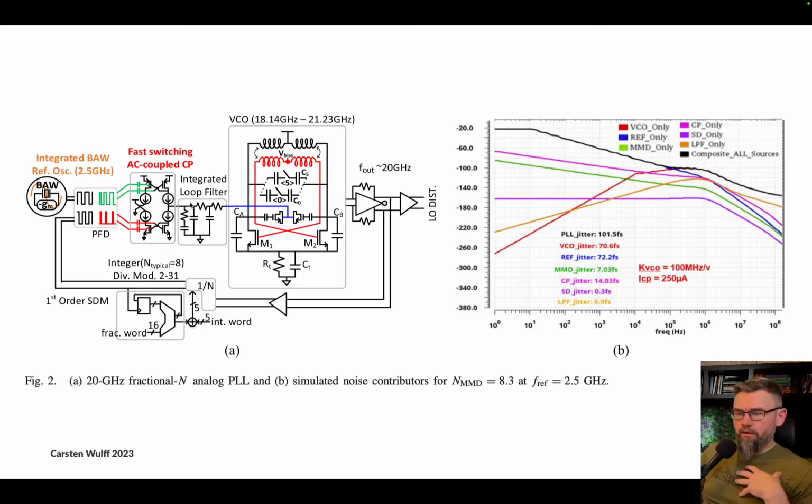Okay, then we have a loop filter, similar to what I showed you, but there is a second filter here, a voltage filter. So the first part is more current, generates a voltage, and then we have a low pass filter. And that feeds into an oscillator where we control the capacitance of some voltage dependent capacitors, varactors, variable capacitors.